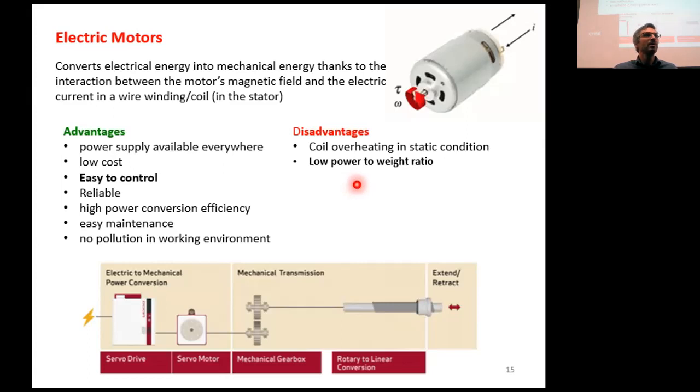Yeah, correct. So big motor, big weight, bigger inertia, and then again to move, you need even a bigger torque. So even a big motor is a chicken and egg problem. And another disadvantage is that some models you will see require some more complex control laws, in particular the BLDC motors.